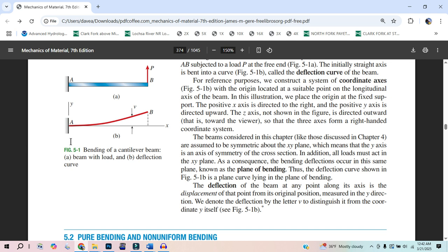That's going to be on our diagram associated with a positive moment. So our shear diagram is negative P over up. Our moment diagram is going to start with our moment, which is a positive moment, and that's P times L. So this one's fairly simple. We go up PL. Then using calculus, we come back to our shear diagram and see that these little areas are negative. So our moment's going to decrease linearly all the way till we get to this point, and at this point there's no moment because it's a straight line.